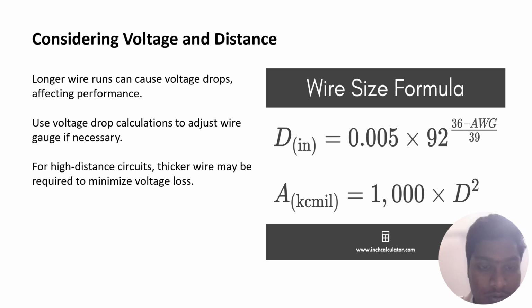Use voltage drop calculations to adjust the wire gauge if necessary. For long distance circuits, thicker wire may be required to minimize voltage loss.